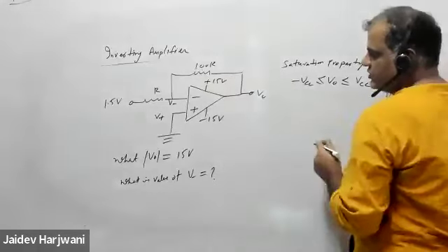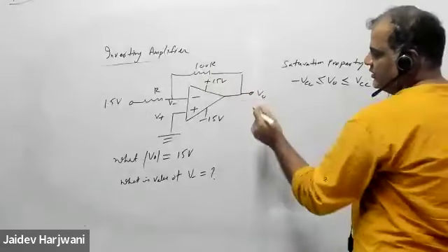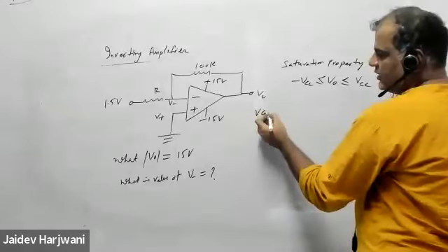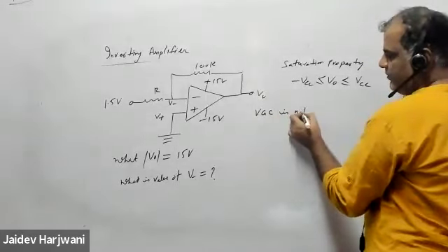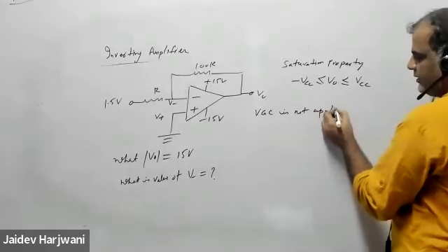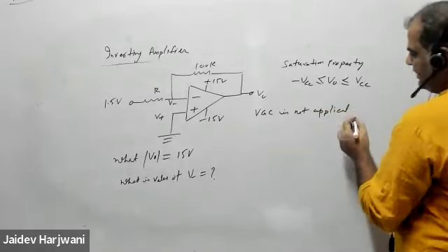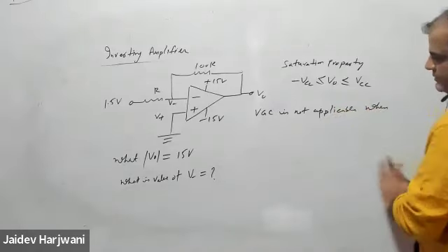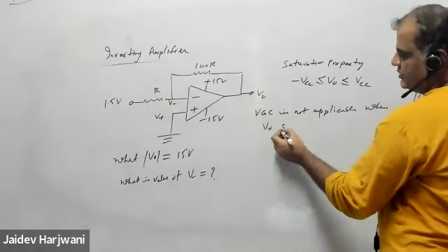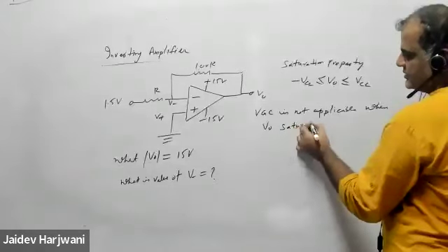It is going into saturation. So the virtual ground concept is not applicable when V naught saturates.